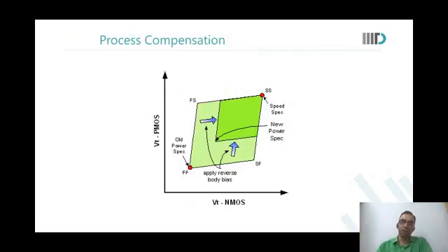Sir, how are we supposed to do this Monte Carlo simulation in the simulator? In Cadence. Yeah, you can look into the user manual. You just have a command called .mc. You tell which parameters you want to vary, and you tell how many simulations you want to do. So it will run the Monte Carlo simulations for you. It is available in the user manual.